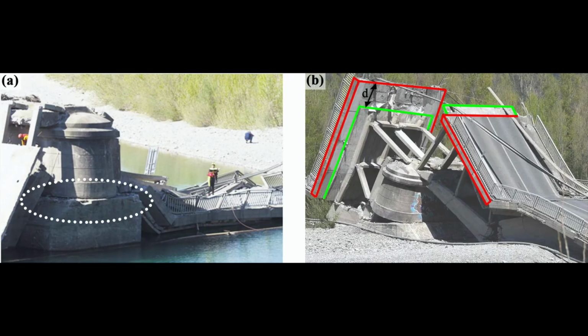So these images, as you can see in image A, represent the misalignment of the piers from the foundation after the collapse. And then along with image B, it shows the outlines of the new and old slab, with the original slab highlighted in green and the added slab in the 1940s highlighted in red. And you can see why they missed the cracking in the original slab, because it was covered by the new, much bigger slab.